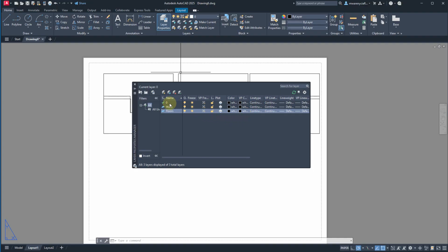Layer 0 is your default, and I can't really explain the full extent of what could happen, or I'll be here for 30 minutes. But you always want to work on your 0 layer, and it has to do with some weird effects that can happen unintentionally if you build stuff on different layers, group it, ship it as a block, and then it ends up in another project, all right?